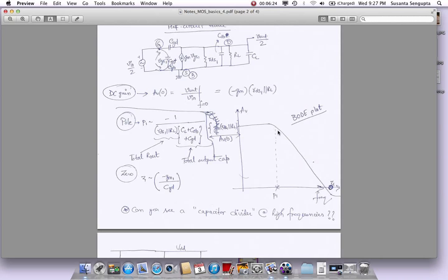Okay, and why is the gain going down? What is really happening is these capacitances are getting shorted over frequency. As their impedance is becoming smaller, they are shunting these resistances. So the current is still there, GM times VGS is still there, but that current has to be multiplied by the total impedance here. At low frequency, it depended on the resistors, which were bigger. At higher frequencies, these capacitor impedances are becoming smaller, and that's why your gain and your output are becoming smaller. It's I times the effective impedance value. And all these capacitances becoming lower and lower impedance just causes the gain to go down.